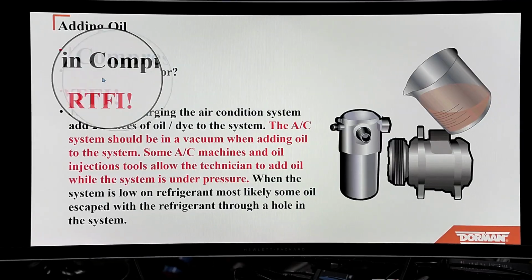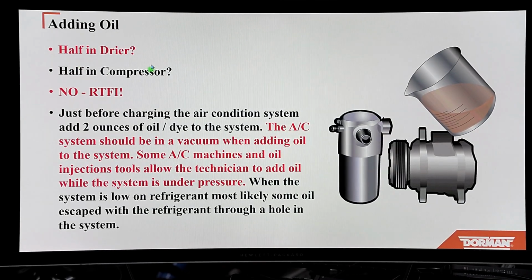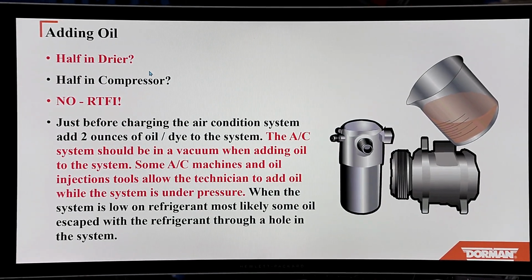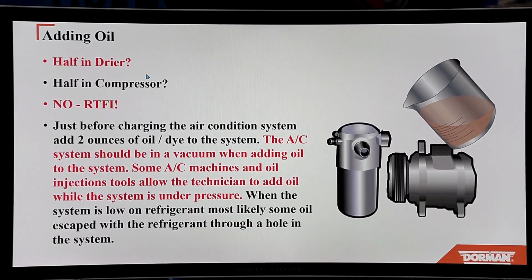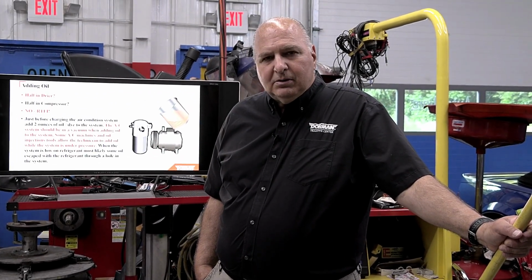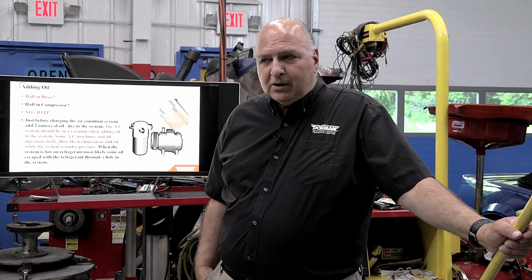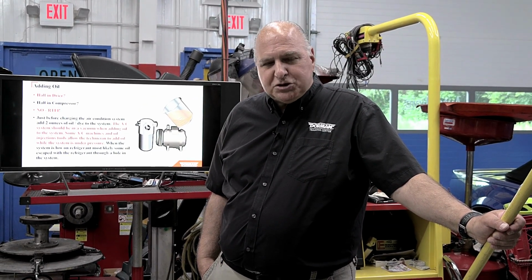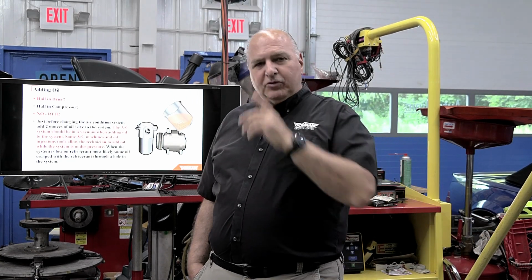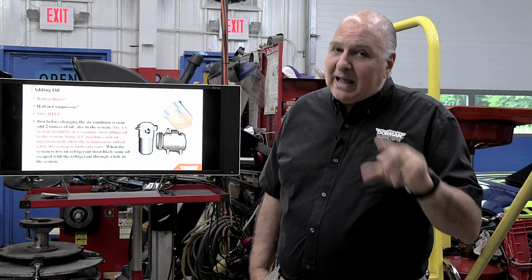Now, when you replace parts, in fact, I caught one of my guys doing this. He put a new condenser in, and I said, hey, did you put oil in? He goes, no, I'm going to put it in through the machine. I go, dude, let's think about this. You put oil in through the machine? What does it have, a little brain in the oil? He goes, I'm going to the condenser. I don't think so, right?